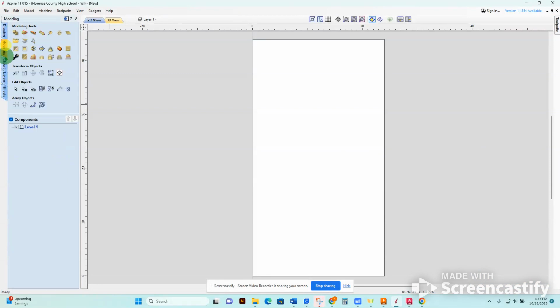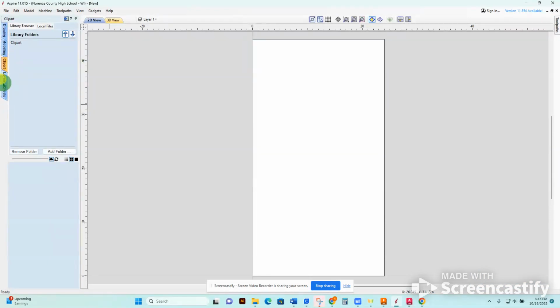Here as well, there's more tabs you can go through to do all kinds of work. We're going to look at layers a little bit, and sheets. So I'm going to do a new layer, and I'm going to rename both these layers. If I slow click into it, click once and wait, it should be able to modify. We're going to call this one the circle cuts, and this one is going to be sign. And then we're going to create one more and call it lettering as well.